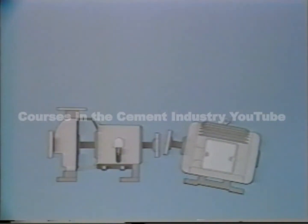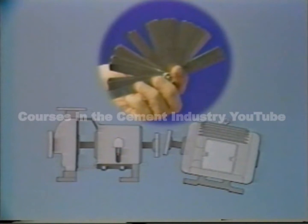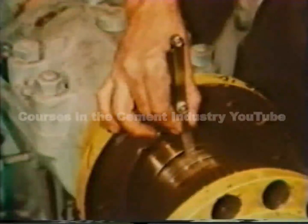There are a number of ways to make the measurement. A thickness gauge like this one can be used to get a pretty accurate reading. By fitting the gauge between the coupling halves, you can detect variations in the distance between them.